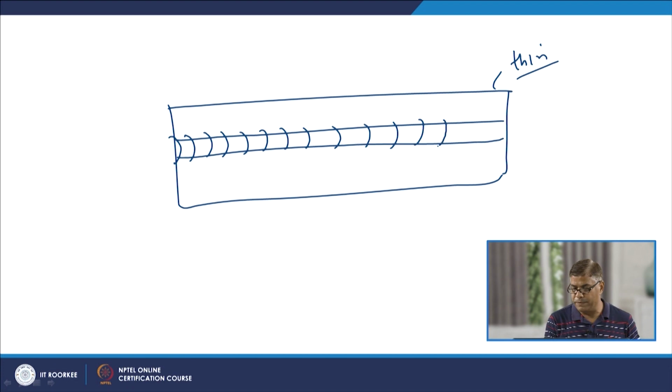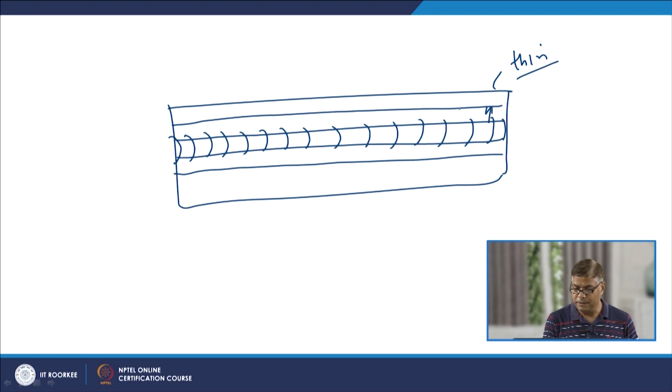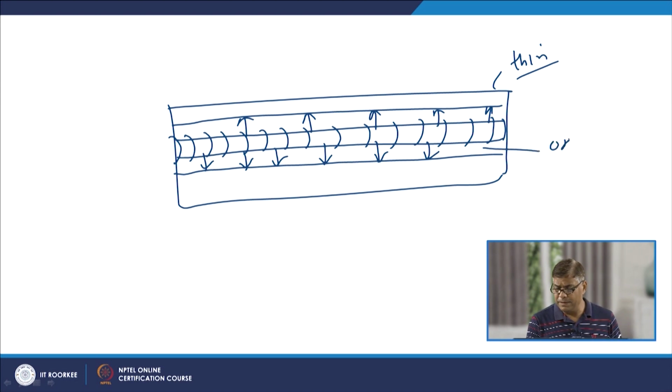Zones near the weld metal will be heated to a higher temperature. So, this is the vicinity or the area which is heated to the higher temperature. Because of this, the stainless steel will get oxidized, and it will form a thick oxide layer on the surface.